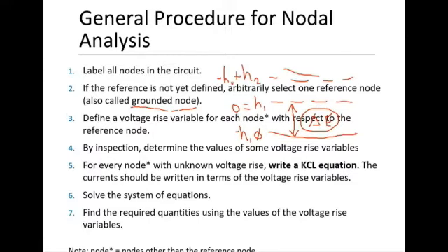So you can set any height to be 0, but the change in energy between those heights does not change. So when solving for voltages in a circuit, you're looking at the potential difference between two nodes. It doesn't matter where you define the ground node, you'll still get the same voltage difference across each element in your circuit. Okay?